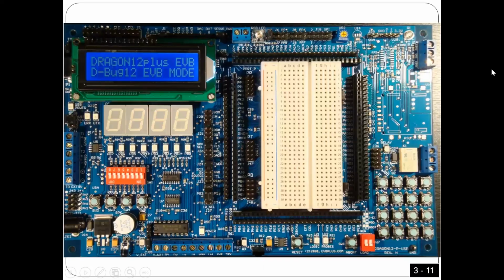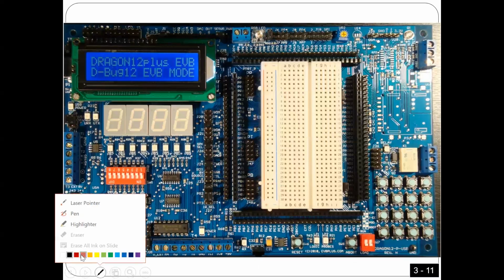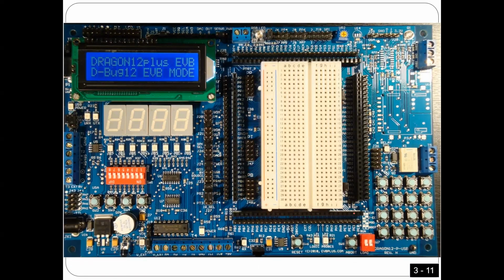Look here, guys, pretty simple. The second one is the IRQ, which is PE1. I told you PE1 is the second one. So here, you have to connect the second one.